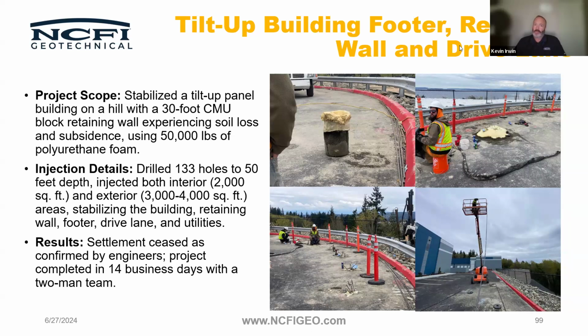But that's always the 1,000-pound gorilla in the room: how much is it going to take? To quantify that, you use all the information that you have at your disposal. That means you need more information than a typical project. On a deep injection project, you're going to need geotechnical information. If you're going beyond 5 feet just to stabilize the corner of a house, versus going 50 feet to stabilize a building like we're looking at here, that's a really different calculation.